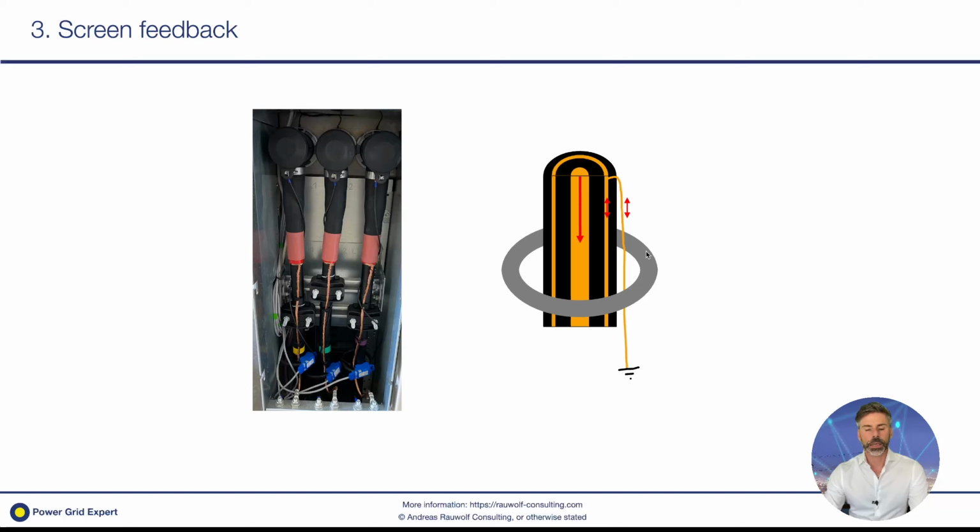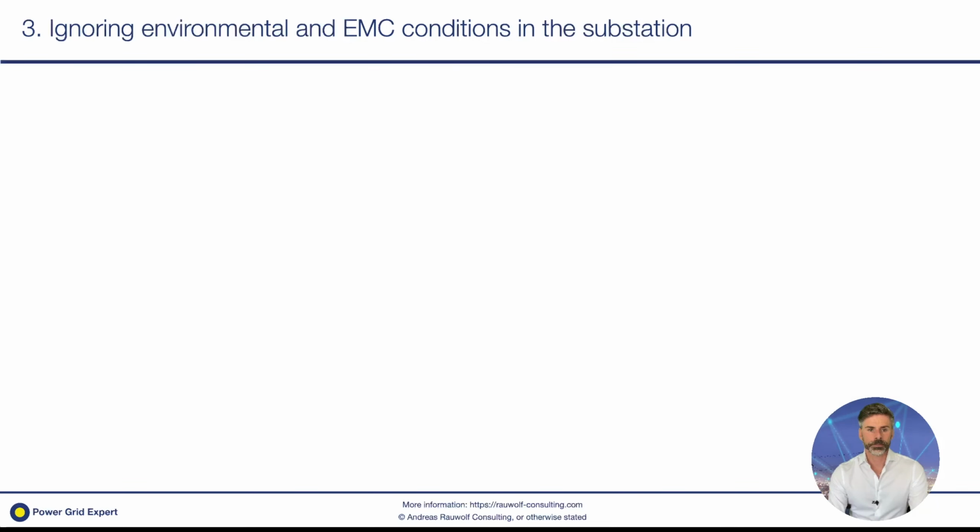The current goes there. Also what we don't want. Also don't go outside of the CT and then back through, then you double the mistake. Also not a good idea. Just think about subtracting what is flowing in the screen, and then you will be good to go.